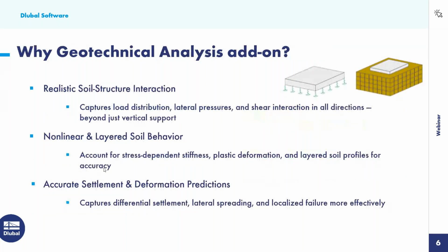So we might be wondering, why would we want to use this geotechnical analysis add-on as opposed to a more simplified approach where maybe we have a slab type element and typically, as we're used to in any FEA program, just applying a spring support stiffness to the base of this element? Well, in comparison, the geotechnical analysis, as we just discussed, will generate these 3D soil solids instead, as we see over here on the right-hand side.